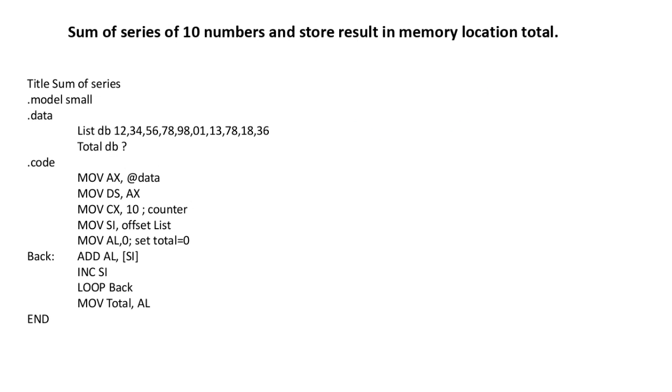The example that I said here: if we have a series of data, how can we use it? We can use an index register, like the SI index register, and we can use a loop instruction. Without loop also we can do it, but loop makes it easy. But is it clear, this program? If we have a series of data, how can we add them together? Is it clear?